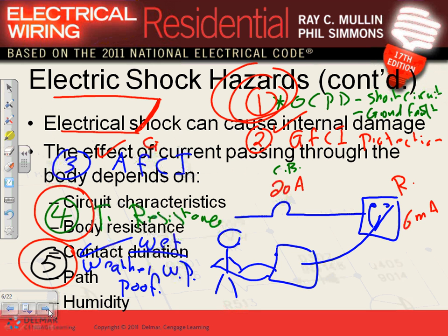So these exceptions came in 2011. A dedicated space behind, non-accessible, doesn't have to have tamper resistance. The height of 5 feet 6 inches, don't have to. If it's part of a lighting fixture, you don't have to. And the 4th one, if you are replacing a non-grounding receptacle, they don't have to be tamper resistant. All other receptacles have to be tamper resistant, GFCI or non-GFCI, the same. Any questions about that? These exceptions just came to be in 2011.